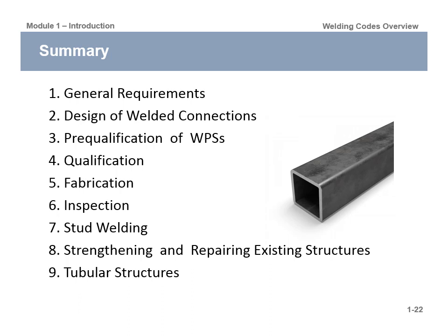Clause 5 is the rules for fabrication. It tells us everything we need to know about fabrication, putting the parts together, what we can and can't do, what needs to be done. Clause 6 is inspection. Visual, non-destructive, ultrasonic, that's all in clause 6.